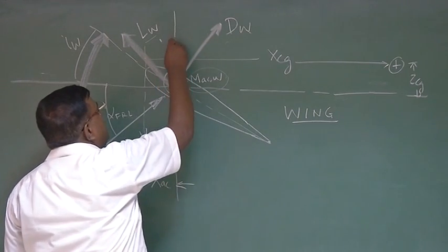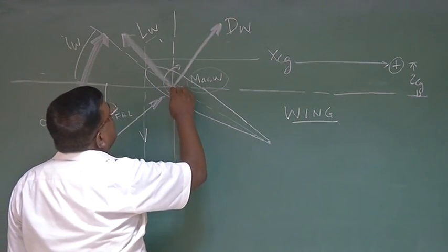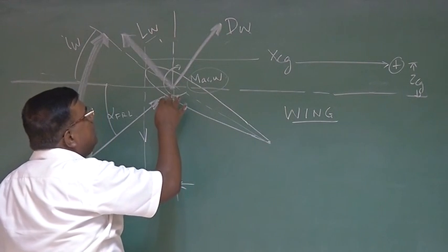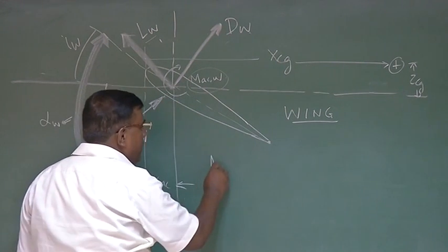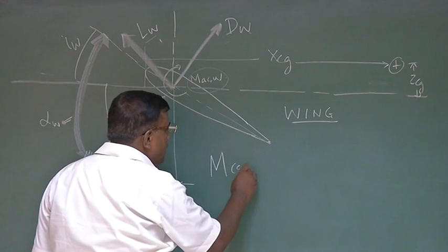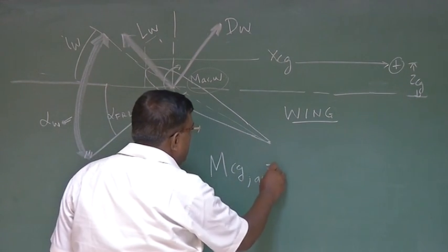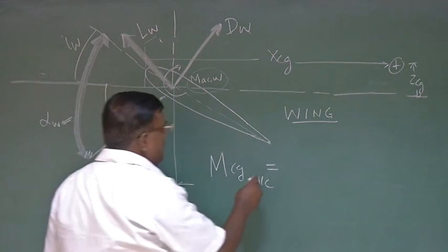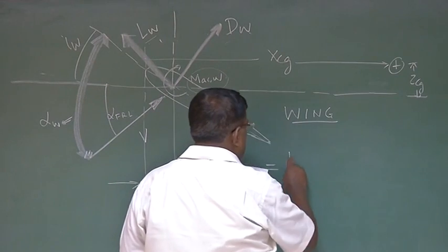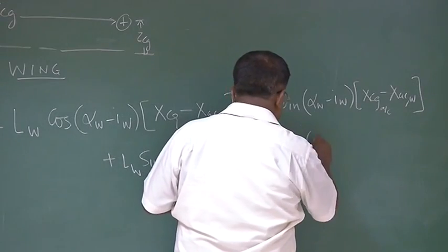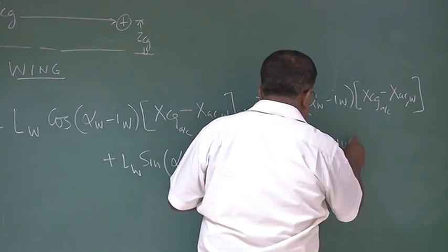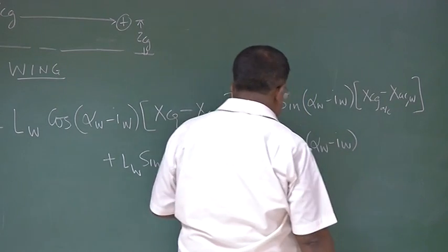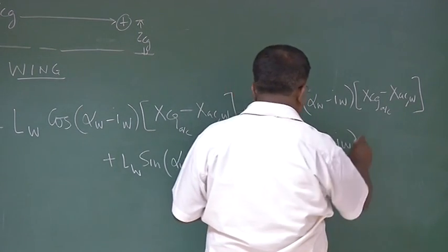We want to find out the contribution of this force moment structure, in terms of writing what is the moment about the CG of the aircraft due to all these wing aerodynamic forces. Very simple. So now if you see here, I can easily write this equation so that I can explain it better. Do not worry about so many terms. You will find soon we'll neglect them and make our life simpler.